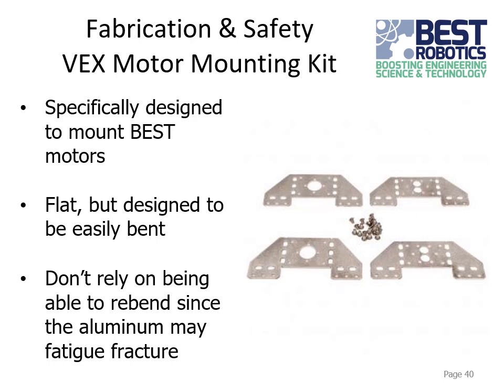Don't try to rebend these, because they're only designed to be bent once, really. So there's kind of two different options. I mean, you could mix and match a little bit, but the two main ways of bending these are either inward, where the little parts at the very bottom go in towards the motor, or you can have them outward, like external, where they bend away from the motor.